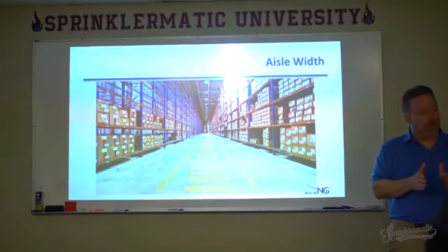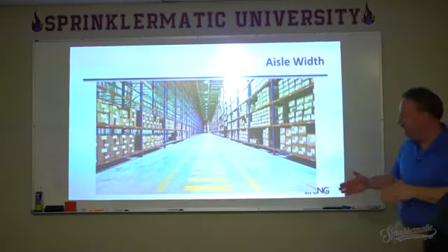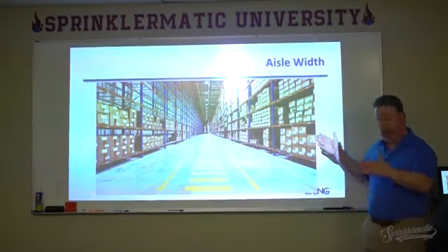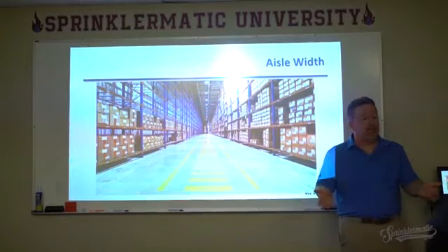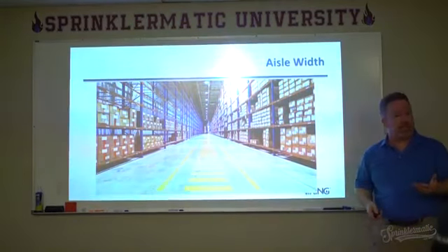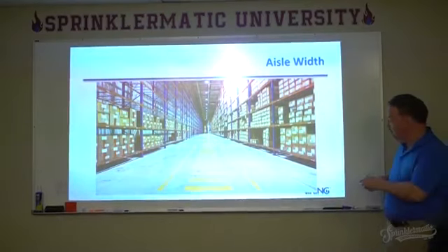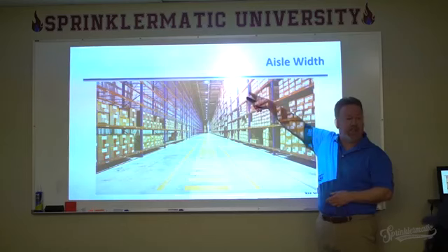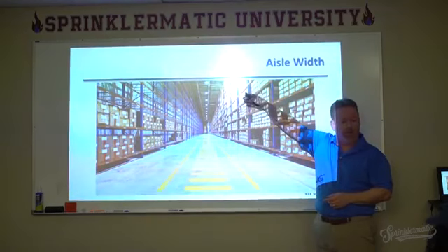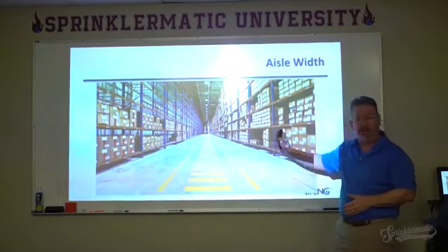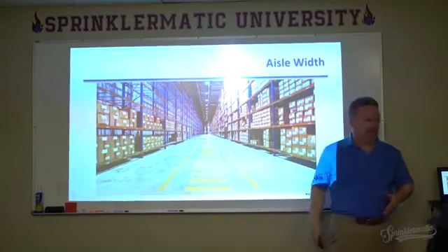Stack them on the floor. Right. How do I limit, get that in there? Well, I can go 4 feet, but what's a 4-foot aisle gonna do? That has an impact on my sprinkler system design. Why? Because if I get a fire going here, and it starts rolling up the outside here, burning this, if I have another aisle only 4 feet away, it's gonna jump the aisle, all right?